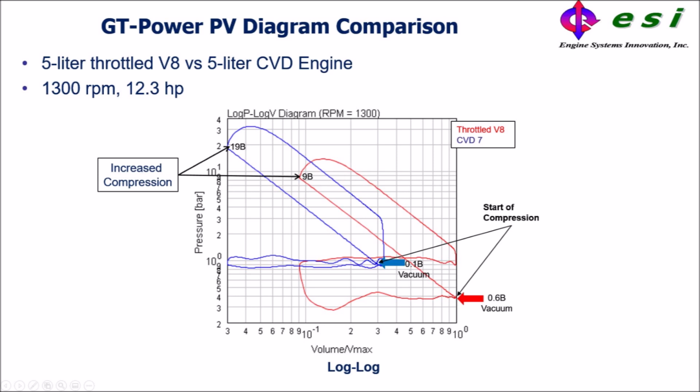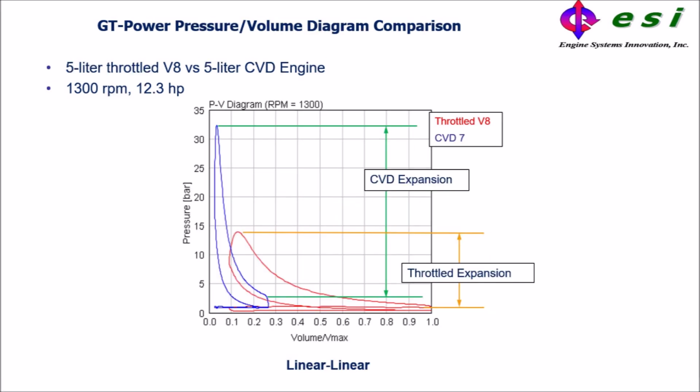Variable valve timing cannot overcome this and somehow restore the 19 bar compression pressure. It simply makes no sense to expand air, then recompress it, as you are downgrading the engine's effective compression ratio. But that is the limitation of fixed displacement. Even the BMW Valvetronic system cannot overcome this problem.